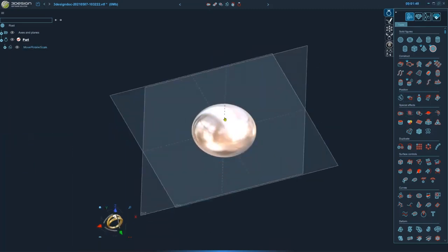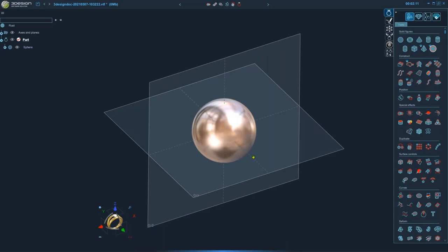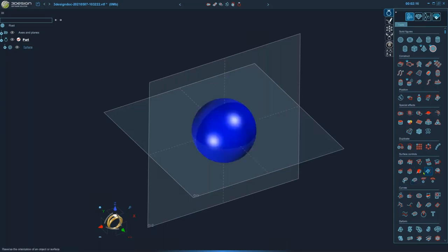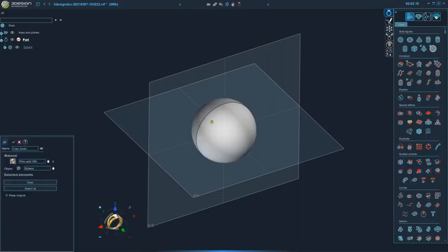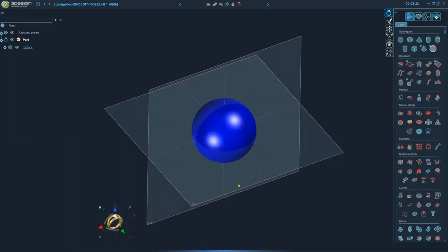But before I do that, I need to worry about seams. Remember, seams are on all objects. I know a sphere has a seam going around the object around this y-axis here. So let me undo that. The fix for that is I want to turn this 90 degrees so that seam is going around the horizontal axis there. But if you don't know that, how do I know where those seams are? The old-fashioned way, of course, would be to use one of our surface tools that displays the topography. And now I can see, okay, there's that seam. But I can't see that while I'm rotating it.